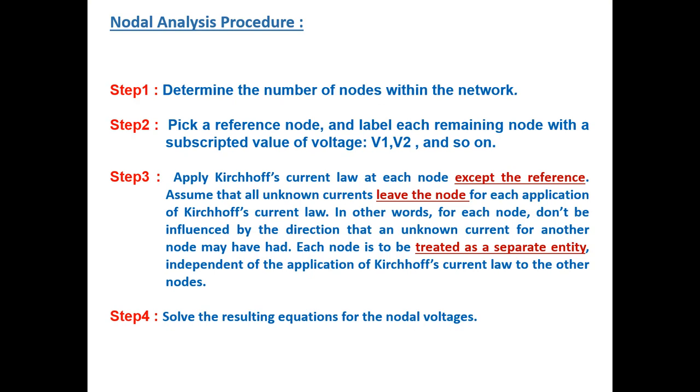There are 4 steps to take into consideration while dealing with the nodal analysis method. First of all, you have to study your circuit and determine the number of nodes within that network. Number 2, you have to pick a reference node.